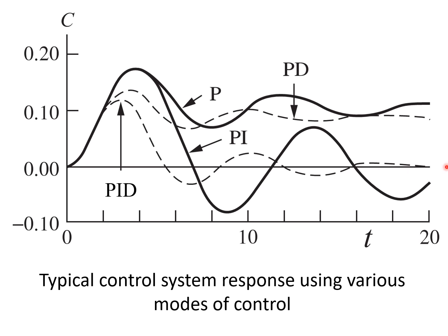Offset is the steady state, that's one issue. But offset alone will not tell you which is the best. If you have no offset, how does the response go before you get the offset? So you will have to use the dynamic criteria on overshoot, the rise time, how fast it goes up, the decay, how fast it decays, and then you have to use the whole spectrum of error, ISE, IAE, and so on. So that's why we need all the different criteria sometimes to come together to make a decision.